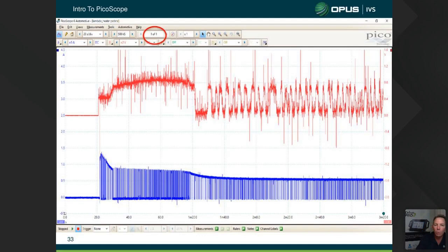Now, it helps if our time base is slow. So the slower the time base, the more information we get on there. A good example: if I'm measuring a bus signal, a CAN controller area network signal, and I have my time base at 50 microseconds, I'm going to fill up those 32 screens in about 4 seconds flat, right?